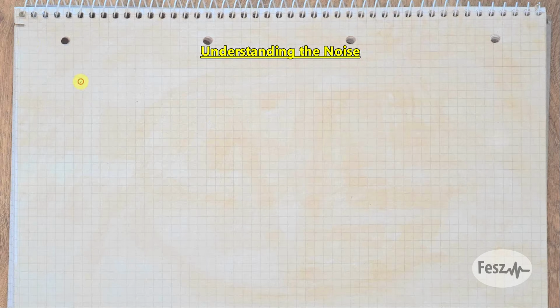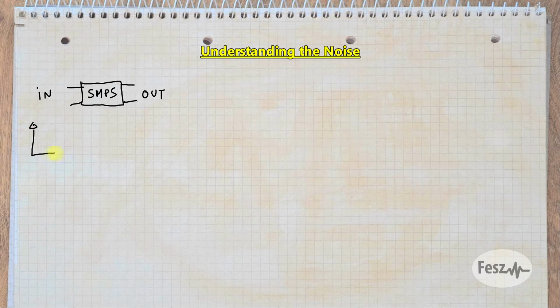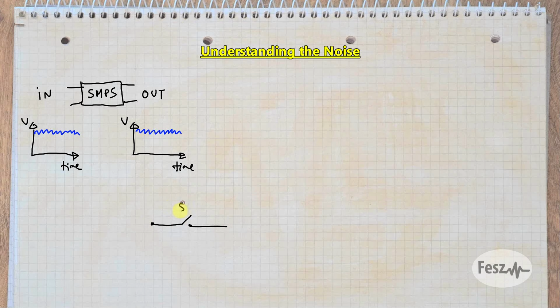First thing to understand is what the actual waveform is telling us and why. In general, both the input and output of a converter will be at a defined average DC voltage, but also have some amount of perturbations imposed over it. There are three main causes why the DC level isn't really a DC. So first, a switching converter usually contains a switch, which switches, and while both the input and the output is connected to something, most of the energy going through the switch is not directly pulled through the lines, which have some amount of inductance and resistance, but rather the energy is transferred from the local decoupling capacitors.